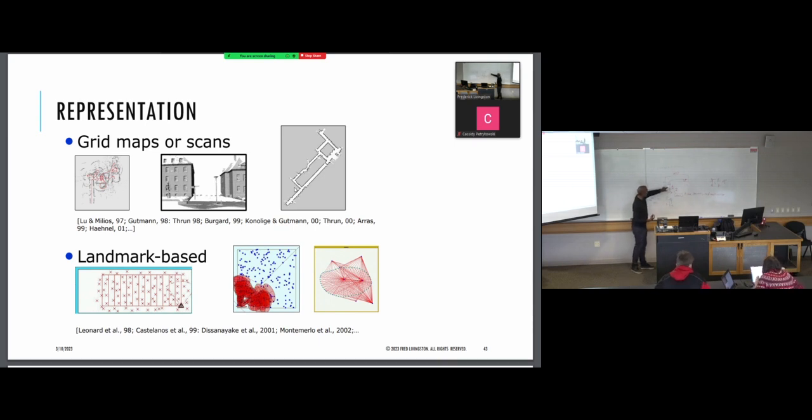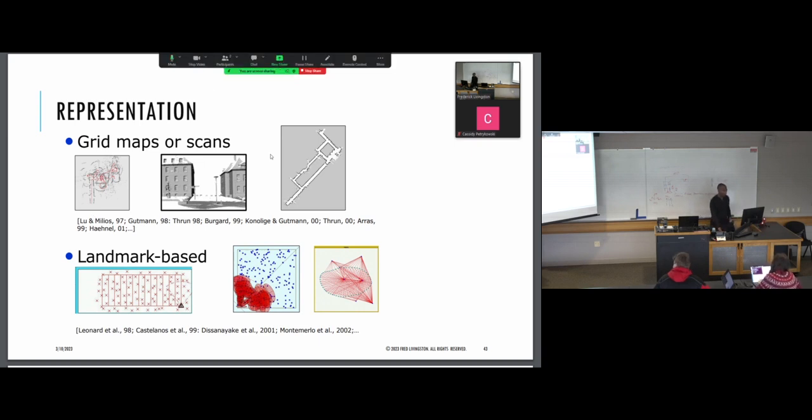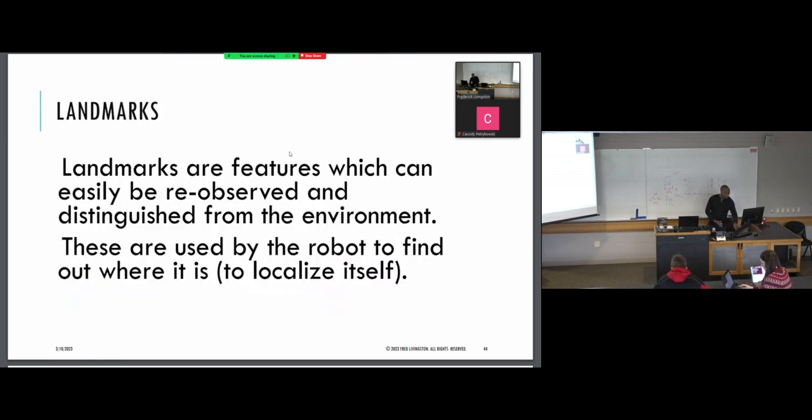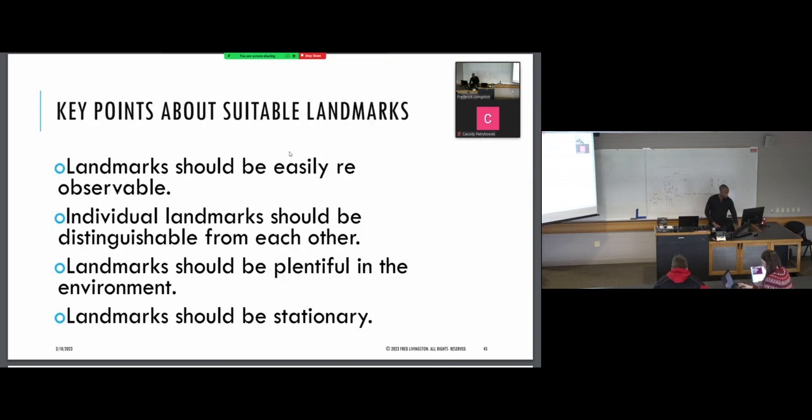It's going to find that whole object and try to get a position for that whole thing. That's one of the parameters you use when you're tuning your system, because it doesn't know what environment it is in or what size it is. So that is grid, and you also have landmark, which is a single point. The algorithm in ROS is a grid map algorithm that's built in, and it's going to give you a map like this. And let's see here. So make sure that it's in a stationary environment when you do your first mapping, which you should have.